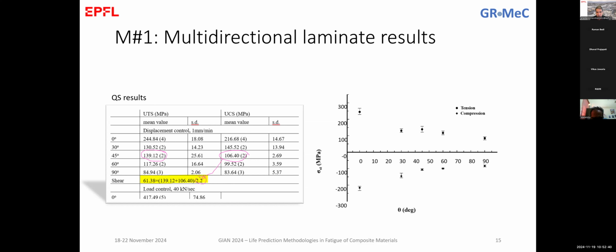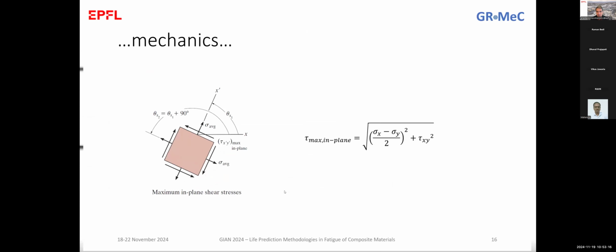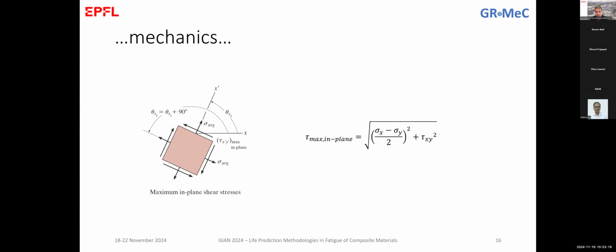So your tensile strength here is 140, and here I have a different differential between the tensile and the compressive stress, but more or less my shear is half of the tensile strength. So you see that in composites, this is again valid as it was for metals. And why is it valid? Because in composites you have the same physics or mechanics as what you have with metals. In metals, this is what you have. This is the typical, this is not related to material, by the way.